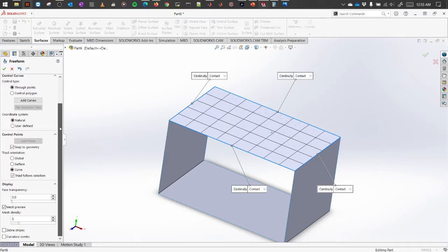Then you want to select one of the curves along which you want to make the changes. So let's say I'm selecting add curve. As you can see, the green line as I move my cursor is the control curve. Let's say I'm selecting the control curve around this point here. If you want to flip the direction, you can just select this one, and you will have an option to select along and create multiple edges or curves.